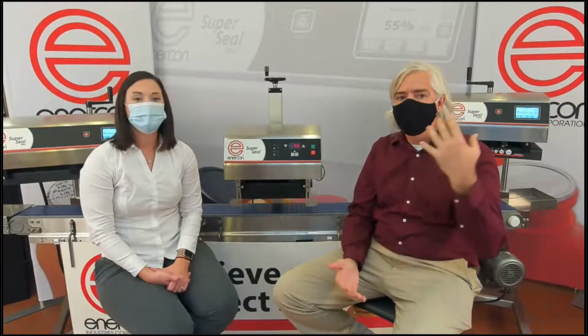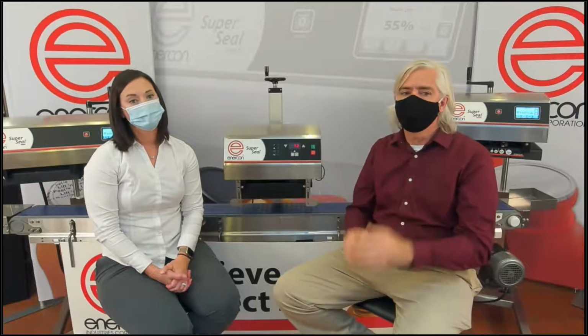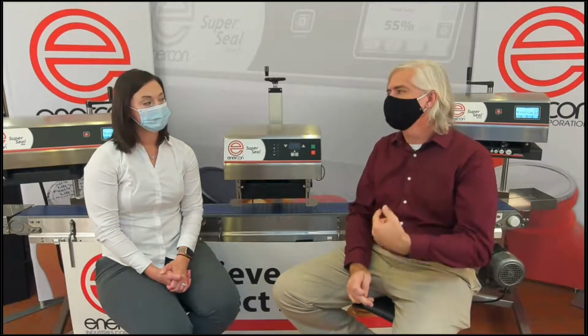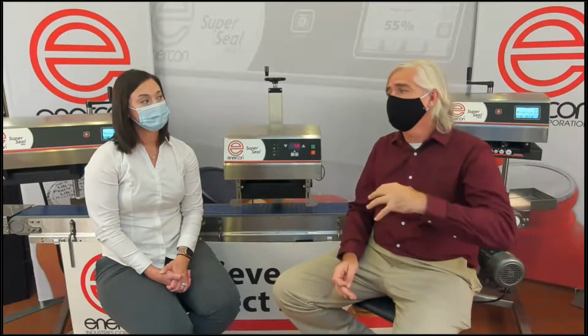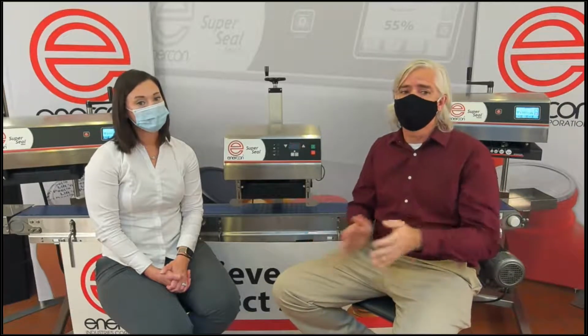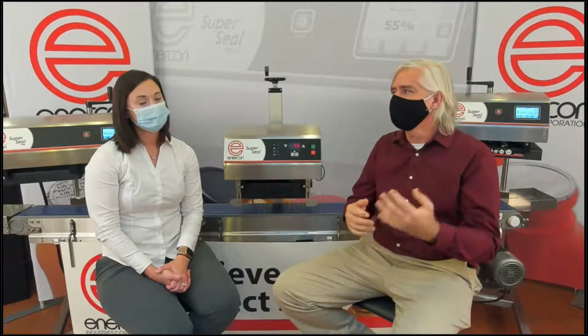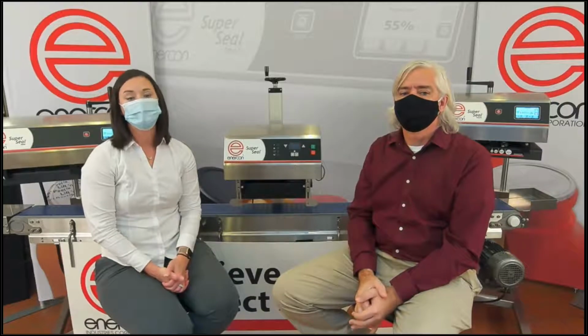Well, an operating window represents the range of power levels that you can use to achieve that perfect seal. You control all the system variables and then run containers through at different output levels. If you've got too little power, you're going to get a weak seal or no seal. If you've got too much power, you're going to overheat. What we're looking for is that right amount of power to get that perfect seal. It's kind of like Goldilocks and her porridge. It's just right. Now let's take a look at a short video that Jeff pre-recorded that covers best practices for sealer setup.